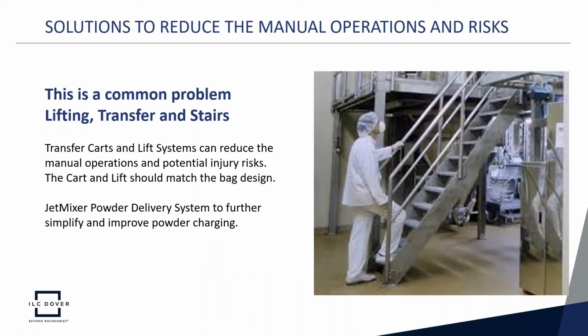So again, one of the aspects we're always looking at is operator safety, and we know in many powder transfer applications, the powder bags are being manually carried in the facility, and a lot of times up steps to a mezzanine or some area where the operator can access the nozzle to make the charge. And so we obviously really want to avoid steps anytime we can. We really do want to avoid operators having to have the burden of carrying a bag of powder, if you will. We know that limits typically are at about 10 kilo for any operator to carry, but we really want to get away from this.